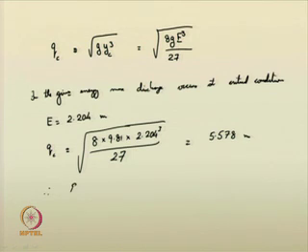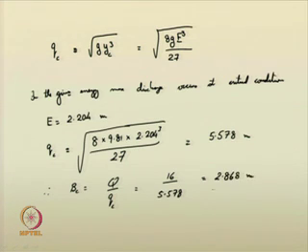So, what is B c then? B c is nothing but the original discharge by q c. So, it is 16 by 5.578. This comes to be around 2.868 meter. So, the maximum constriction, or the width can be constricted up to 2.86 meters. It cannot be constricted beyond that. If we are constricting beyond this, the elevation of the water gets increased. Thank you.